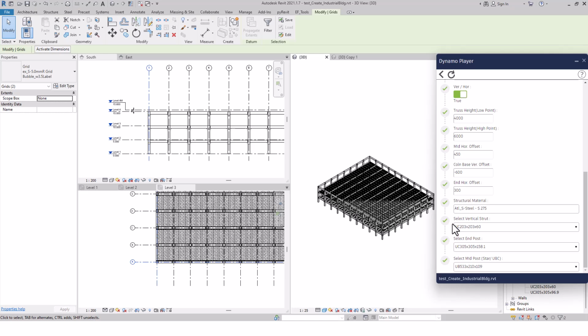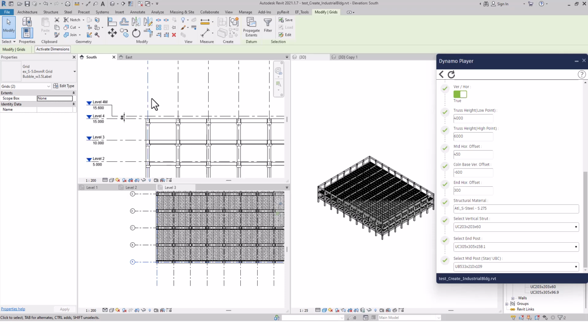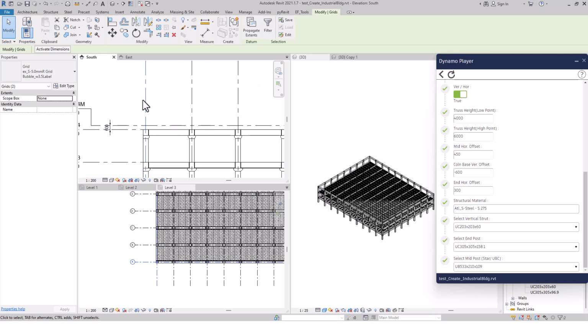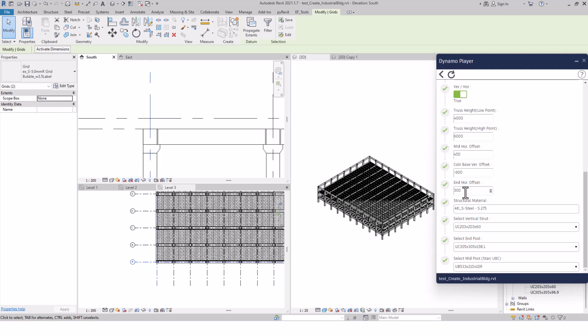Then the column below the reference level is going to be -600, so put in -600, and the last truss is going to appear like that. So the last vertical members of the truss we want to offset from the grid by like 150, so that we have more space over here, so we can provide the parapet walls or something over there, right? So our last vertical member of the truss is going to be somewhere here. The rest will be at the grid line.